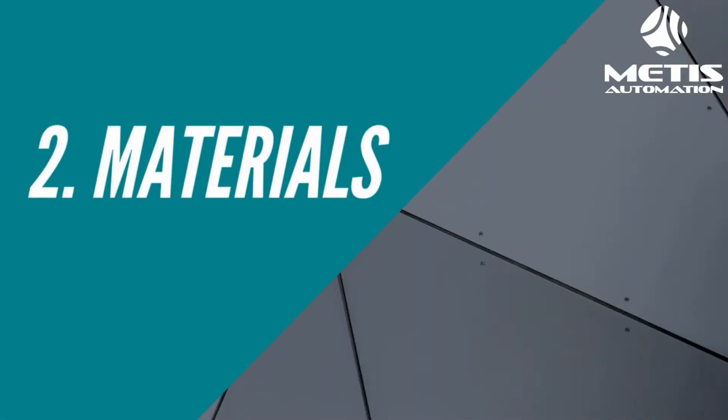Number 2 is to look at the materials coming into your factory. This is often the number 1 cause of variation in your manufacturing process. So are your material suppliers subject to strict quality controls and inspections? That's number 1. Number 2 is, do you have multiple suppliers? And if you do, that's a sensible thing, because you don't want to be completely reliant on one supplier, but is the quality or the consistency of the materials coming from both suppliers the same? Is one slightly better than the other? Investigate into that and see, are you getting consistent materials into your process? That's going to be key to ensuring you get good quality out of your manufacturing process.